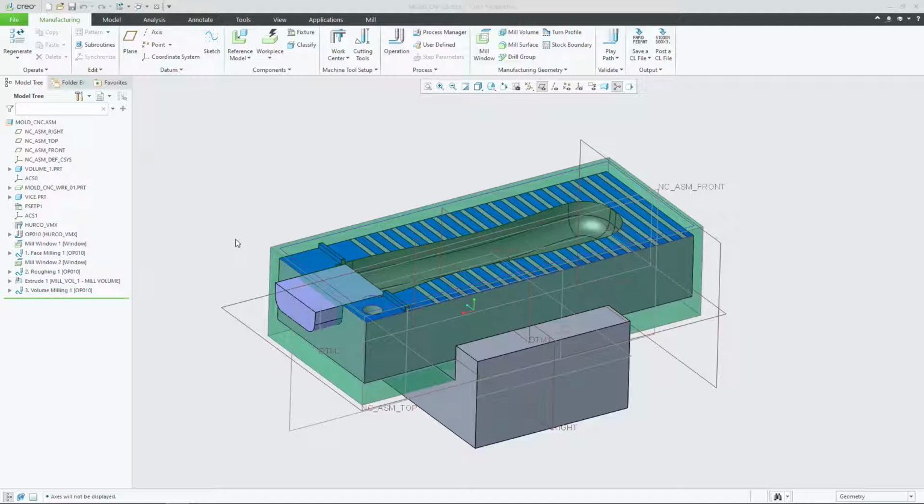In order to do that, we can run a material removal simulation on all of the sequences that we've created, and the way that we do that is go up to the operation level here above the sequences, and if we click on Op 10 we can then do a material removal simulation. We click there.